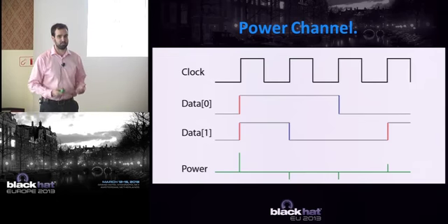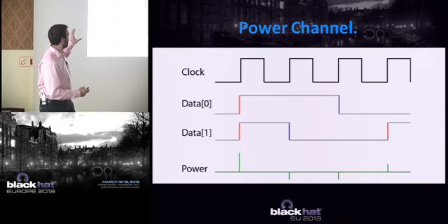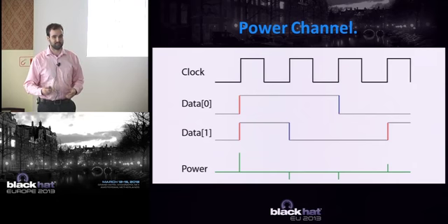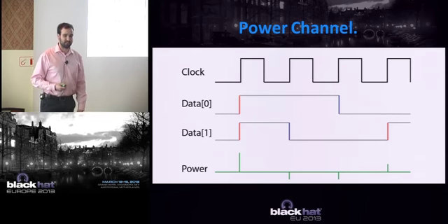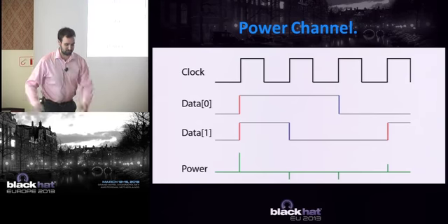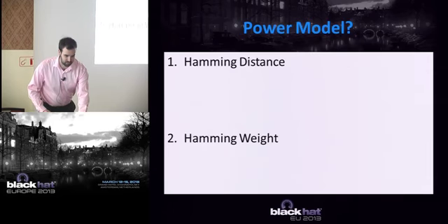So this very basic observation is everything you need to know about power analysis. This is the root of why it works: it physically takes power to change the state of a normal data bus. And based on this, we can break everything else, which I'll explain next.